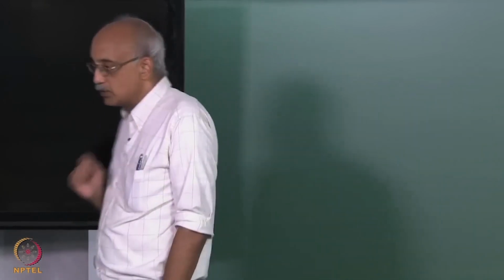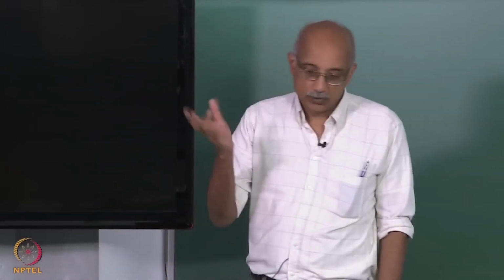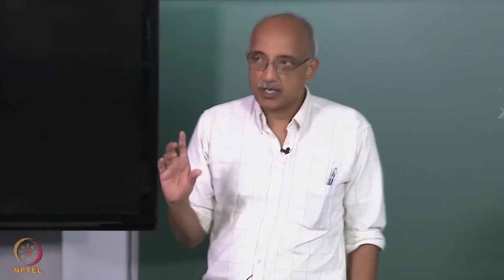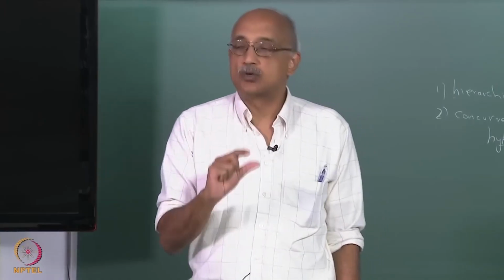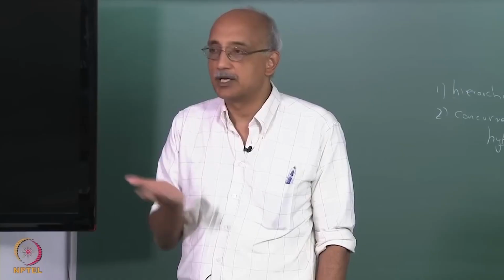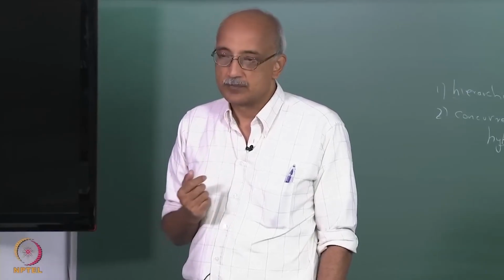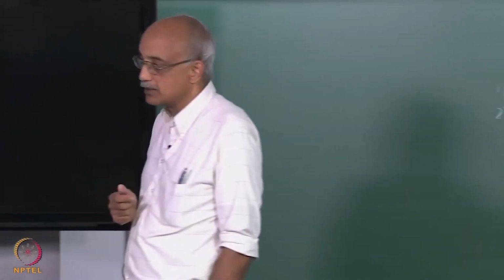and that is where CVD in particular can come in very useful. I mean, you can do the same thing with molecular self assembly, but it is going to be much more difficult, much more laborious, time consuming, expensive and so on. Whereas with the CVD process, we know how to do this. We know how to control the conditions of the reactor to be able to deposit films of known composition and thickness. So, it is very easy to do a layer by layer build up of a nano dimensional film simply by exercising controls over the operating conditions of the reactor.